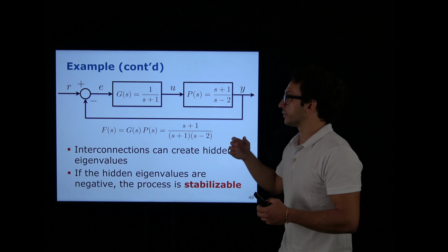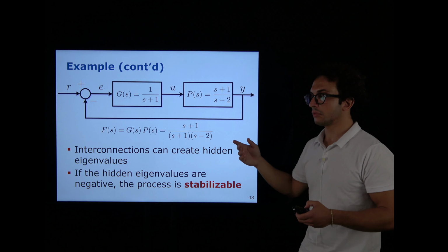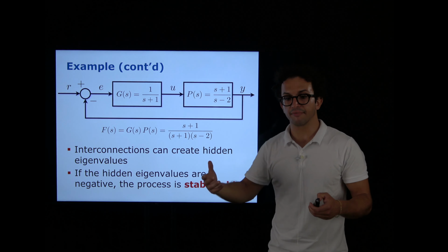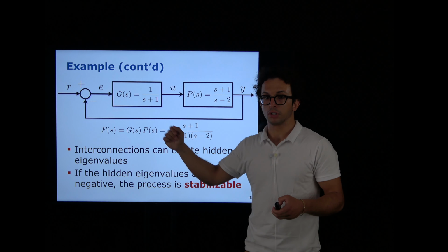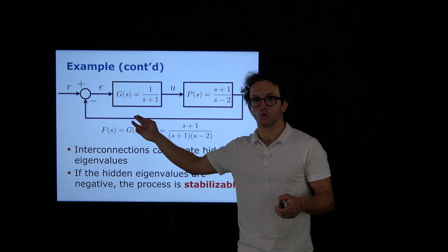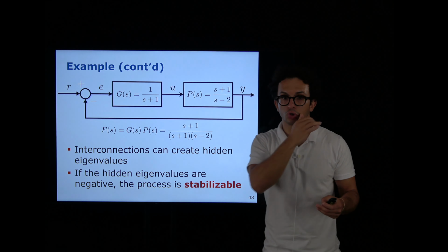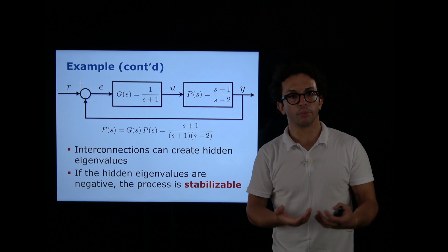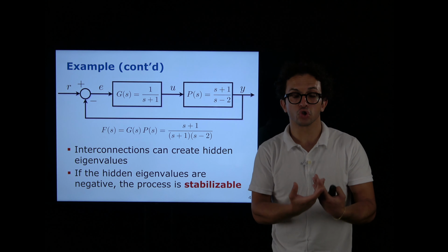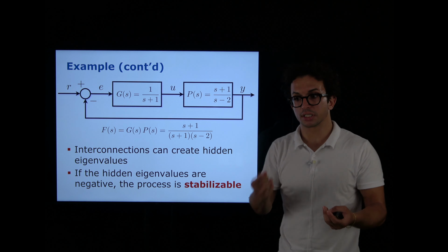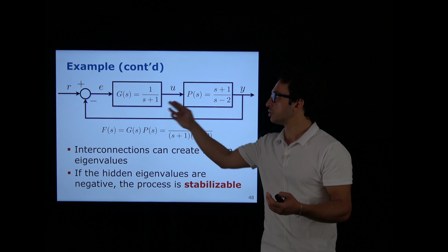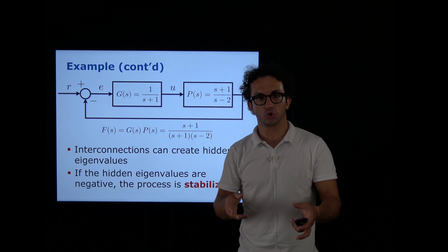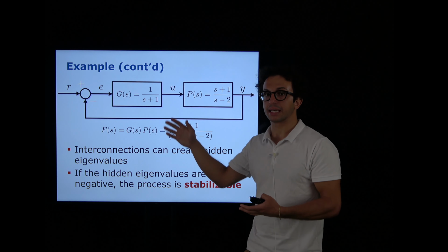Why? Well, intuitively, it's a simplification of an eigenvalue that comes from the controller. So the eigenvalue belongs to the controller. Since it belongs to the controller, it's something that you can actually design, so it's not uncontrollable, because it is the controller itself. It just happens to be a simplification, but it's something you can tune in the controller. So it's not uncontrollable, but it's unobservable.